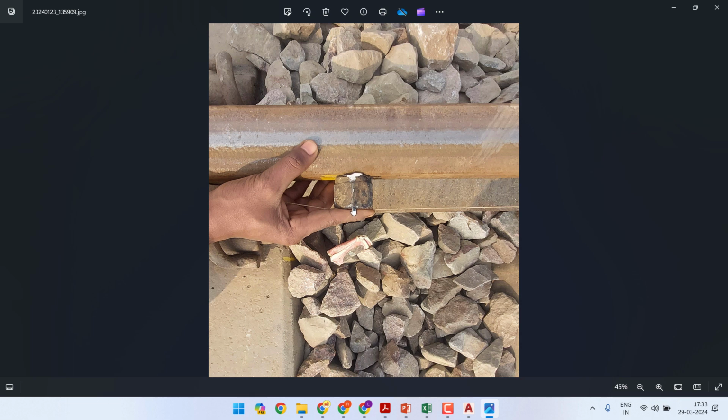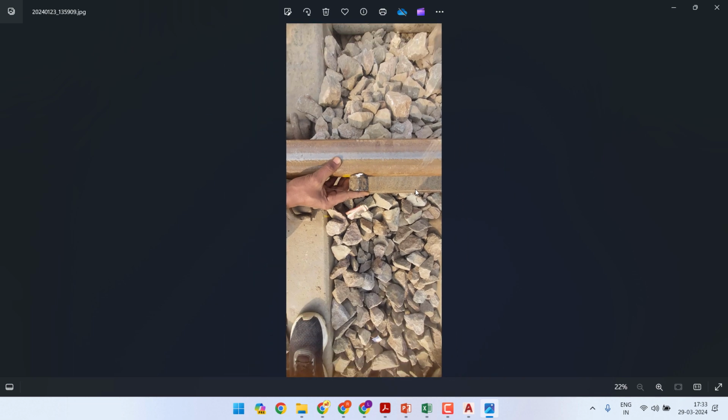So for that you can use two bolts of same thickness like it is placed here, and this will be the offset, and since both nuts are the same, the offset at the two terminal stations will be the same. And the difference between this offset and the value you get at the center of the thread will give the proper versine.